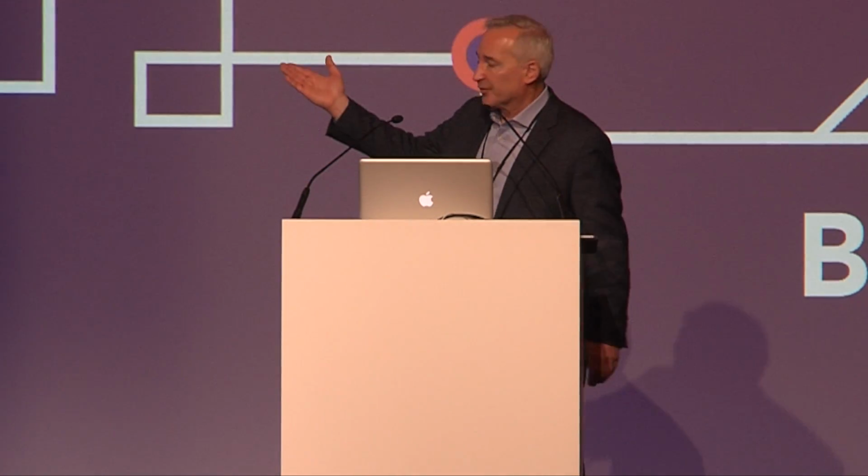Well, first off, the Drawing Explorer in BricsCAD, which, by the way, has been around for a while, but is greatly improved in V18. All your metadata in one place, the ability to preview layers and their layout, comparing dimension styles, and most importantly, a great function, copy data between different drawings that are open in a single session.